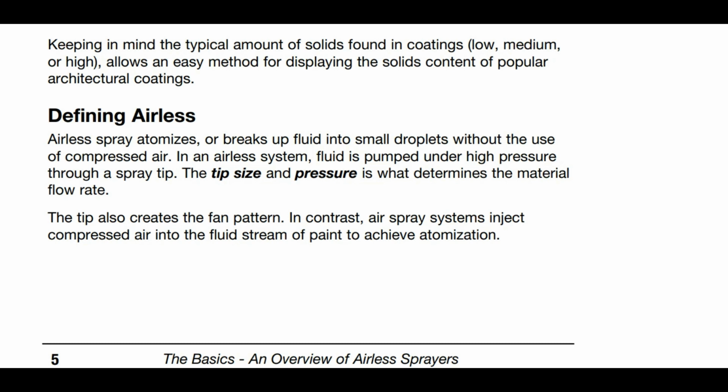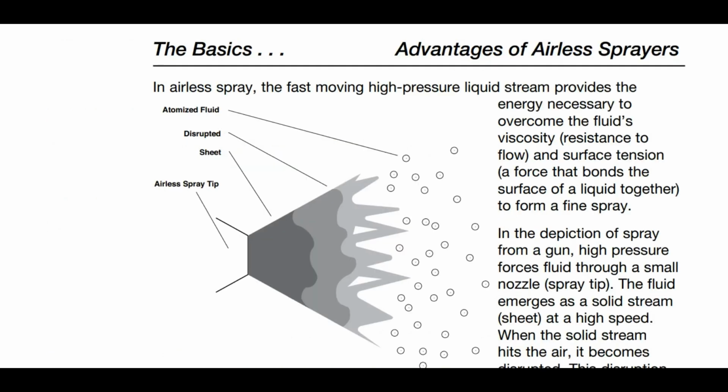In contrast, air spray systems inject compressed air into the fluid stream of paint to achieve atomization. In airless spray, the fast-moving high-pressure liquid stream provides the energy necessary to overcome the fluid viscosity and surface tension to form a fine spray.